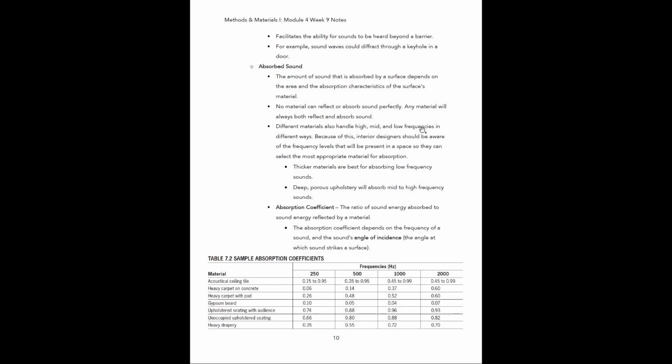Different materials also handle high, mid, and low frequencies in different ways. Because of this, interior designers should be aware of the frequency levels that will be present within a space so they can select the most appropriate material for absorption. When you're designing, you're going to know the functionality of the space, and that will give you an indicator as to the frequency of sounds that will be present within the space.